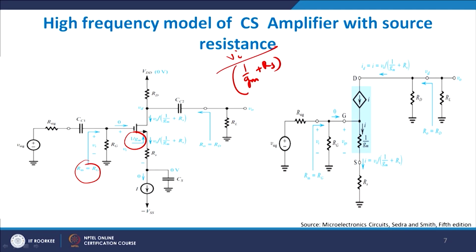and then if you divide Vi, the input voltage, by this quantity, it is basically the current which is flowing through this resistor R, right, and that is what the current is. Now since the current has to be the same, I see that Vi into this quantity will also remain the same. So on the right hand side R0 will be equal to Rd, which is basically the input impedance which you see from here. Now if you replace this MOS device by its corresponding T model, then we say that I will be equal to Vi upon 1/Gm plus Rs, total current flowing.